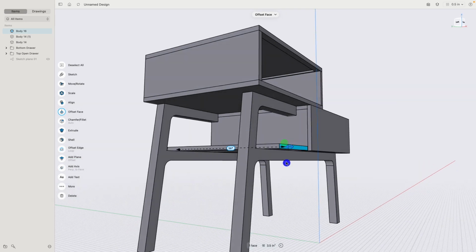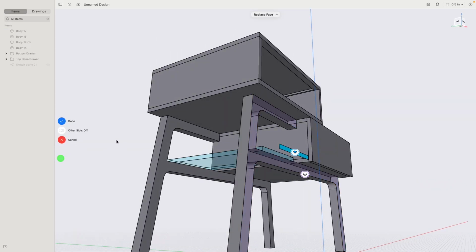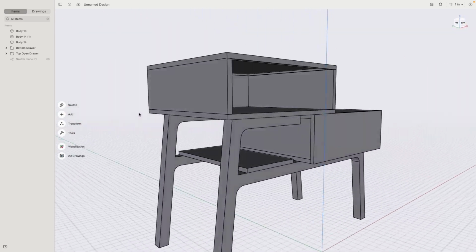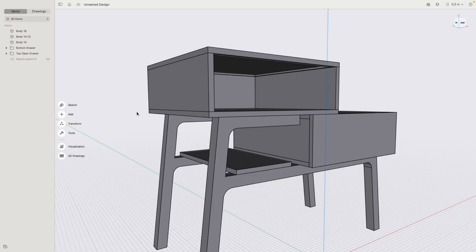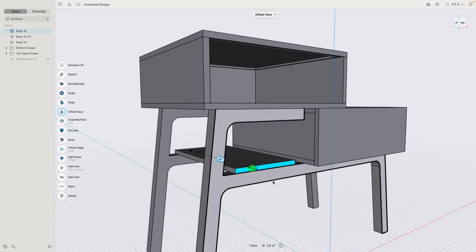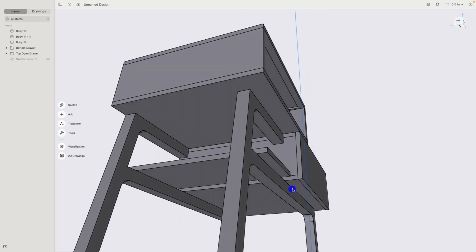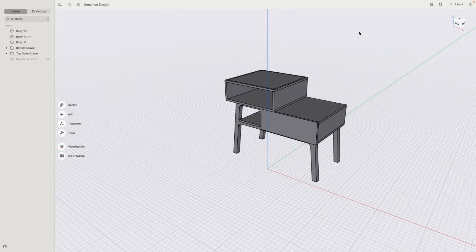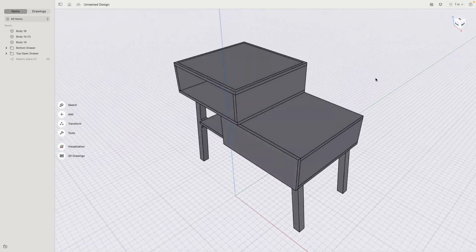Hide this. This board I will match via replace face onto there, so it's perfectly flush and it's a little bit more inside. So I don't really work with dimensions or measurements. I simply use the replace face to match this. And then if I want, so this is 14, 15, we give this a 1 inch overhang. Very good. Okay, beautiful. So you see, this is how quickly we can create a frame construction everything sits on by using a very simplistic sketching approach, trim everything, and then extrude and use the align command to position everything into space.